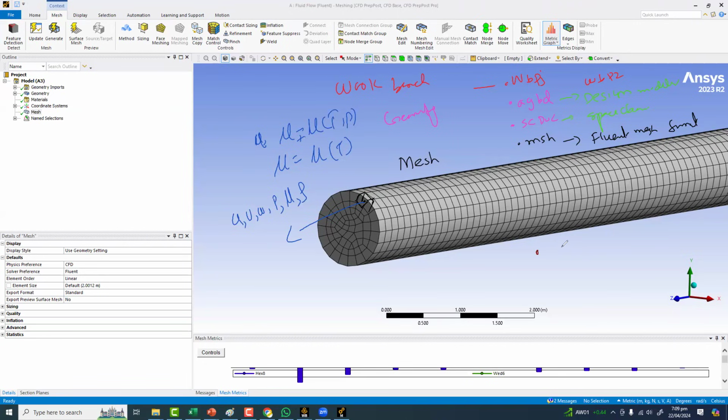Okay. So when we solve a case inside Fluent, it has two files. One is the .cas file, the file name and .cas. This is the case file. The case file is equal to the mesh file .msh plus the settings you make in the file, like boundary conditions, turbulence model, these things. And then we have one extra file, that is .dat. Once you solve the case, we have the dat file, that is a data file, and the data file will contain the solution data. The full form is data, and it contains the results.